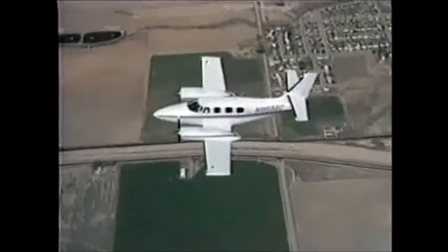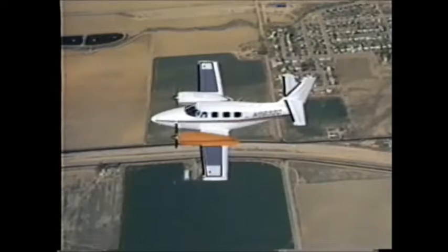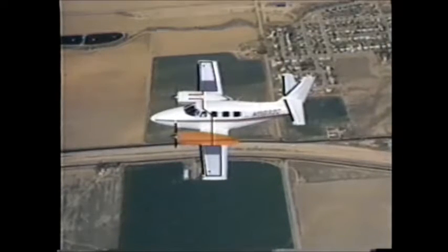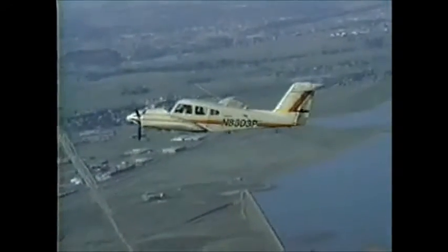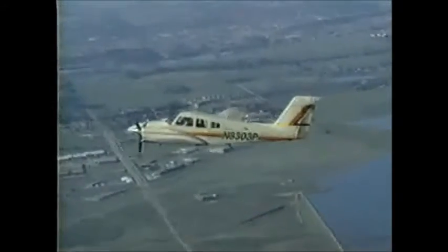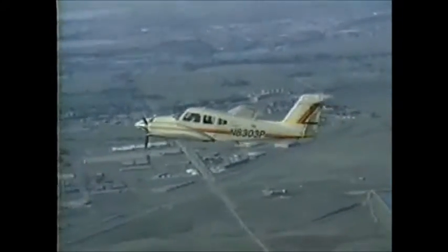For a long flight, use the fuel cross-feed system on the aircraft to maintain fuel balance. You especially want to avoid having a heavier fuel load on the same wing as the failed engine. As you get close to the airport, plan for the approach and landing well in advance and fly a stabilized descent to the traffic pattern.